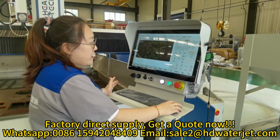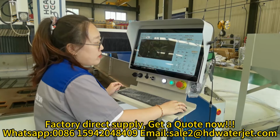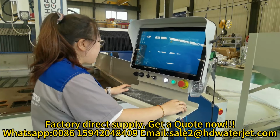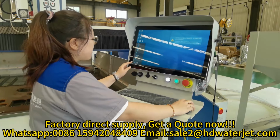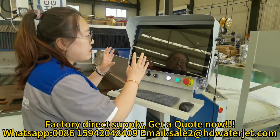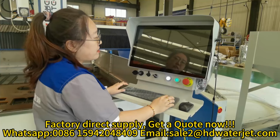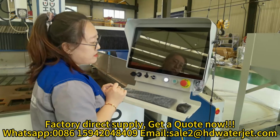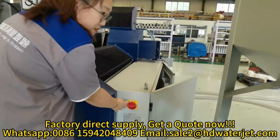After your whole work, when you want to close your machine, you must close your software first. All close. And then open this part to make the power close. And then we need to wait for it to close fully. And then there is no data showing on the screen. Then we need to push this green button. And the second step is to switch this one off.